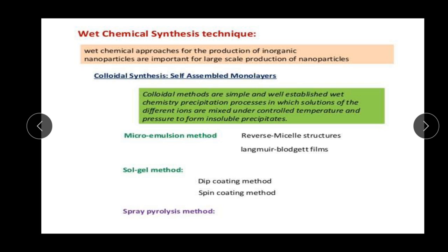A typical example of the formation of nanocrystals is titania powder via hydrolysis at lower temperature. Once the solution becomes saturated, the crystallization of the titania takes place either through homogeneous or heterogeneous nucleation. In the latter case, crystal seeds are added to the solution to promote the crystallization of titania nanoparticles.